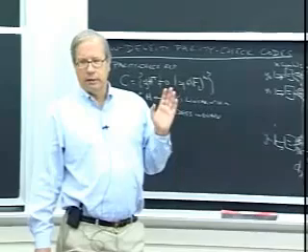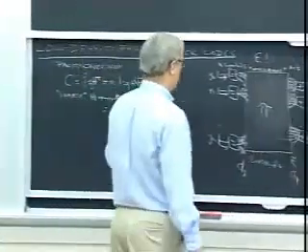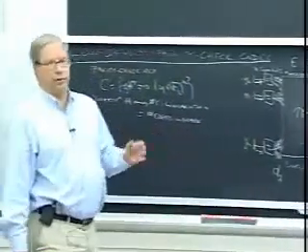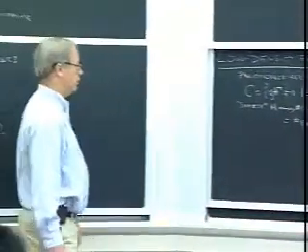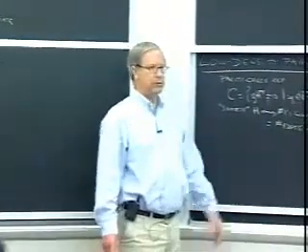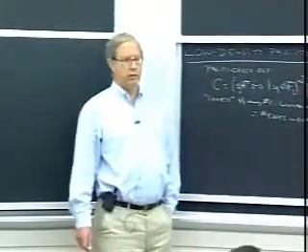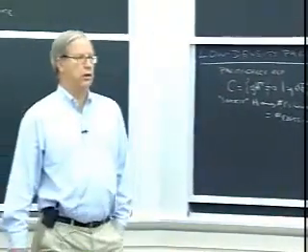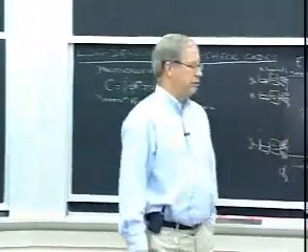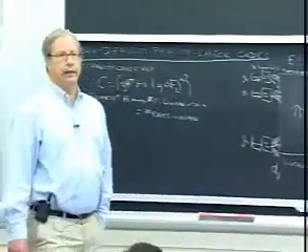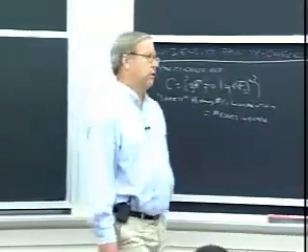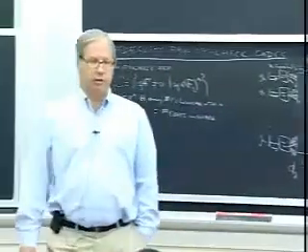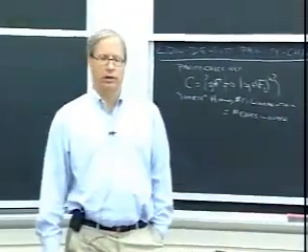One characteristic of low-density parity check codes is they tend to have good minimum distance. They tend to have a minimum distance that's sort of what you would get in a random-like code, which goes up linearly with the block length. So for a rate 1/2 code of length 1,000, a random code would have minimum distance about 110, and a low-density parity check code would typically have, maybe not 110, but a large minimum distance, unless you were just unlucky.